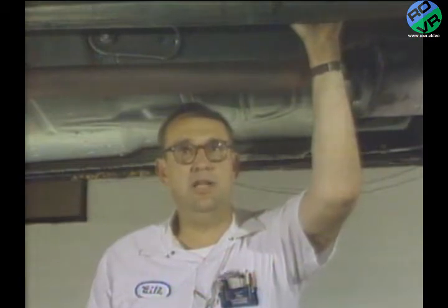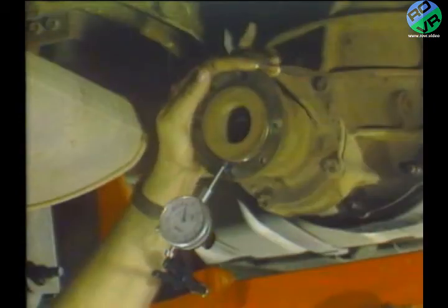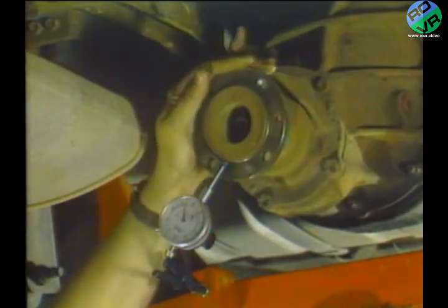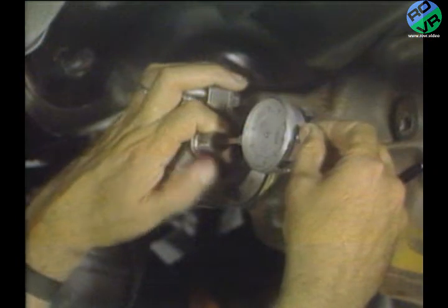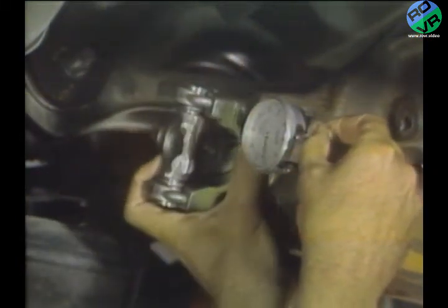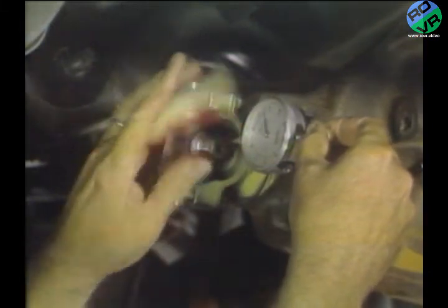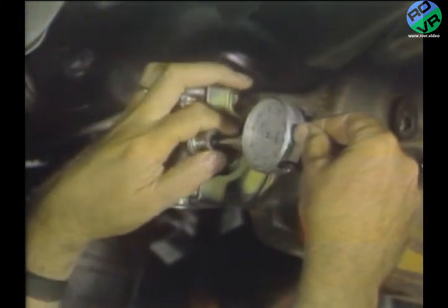Yes, driveline runout and driveline balance diagnostic checks are the most common methods of diagnosing and fixing driveline NVH problems. The other 2 checks you may occasionally encounter when diagnosing driveline NVH problems are for companion flange runout on the double cardan U-joint or companion flange runout on the standard U-joint. A second method for measuring companion flange runout on the standard U-joint is described in the Technical Service Bulletin number 38.